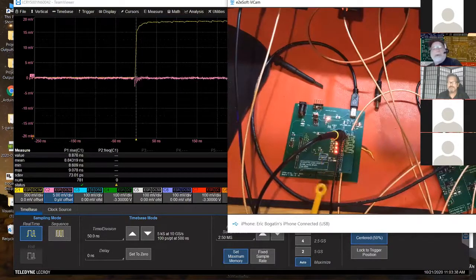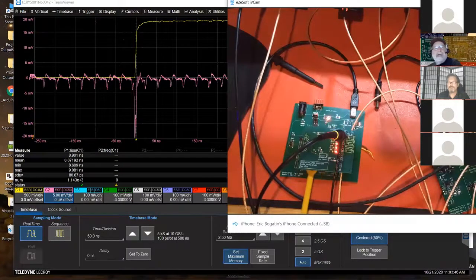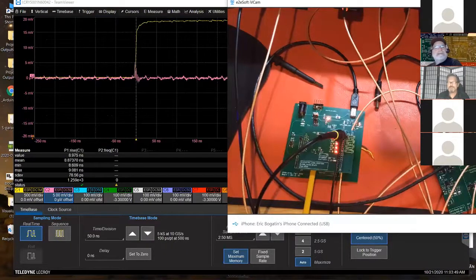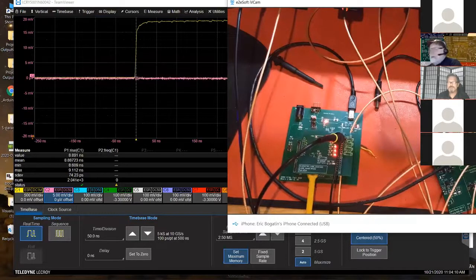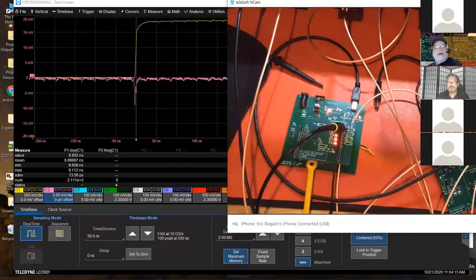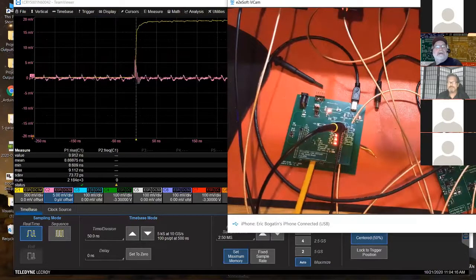If I look at the board, however, you're going to find, oh my gosh, I'm looking underneath the board. There's a lot of I/O current switching. And if I go elsewhere on the board, oh my gosh, look, we're seeing something else going on. We're seeing clock edge noise. Doesn't mean the clock is radiating, but what it means is there's some other source of near field emissions at the clock frequency due to the core logic switching, probably in the power distribution path. And so by looking with the near field probe, we're able to pick up not just the I/Os that are switching, but also other sources, predominantly in the I/O.